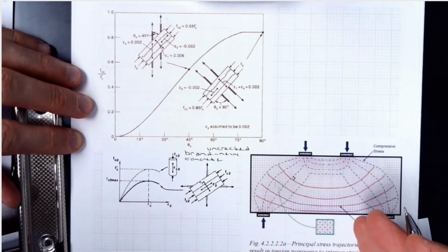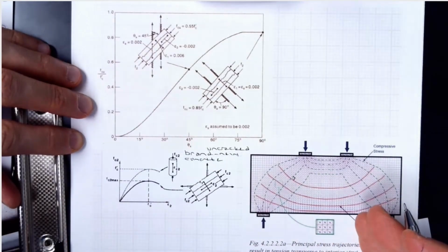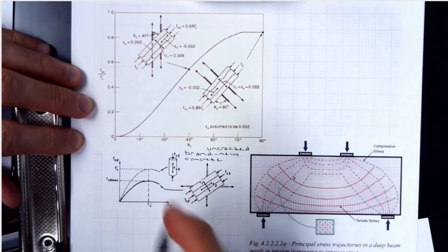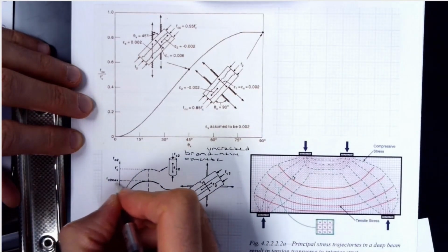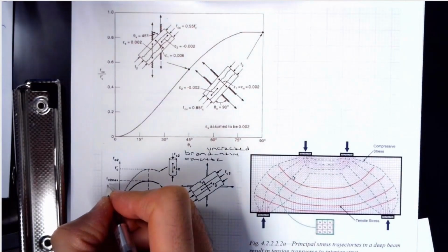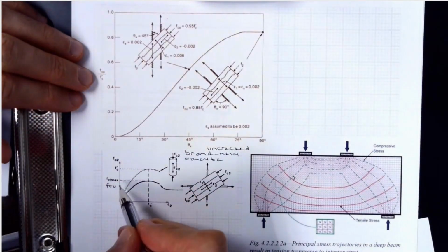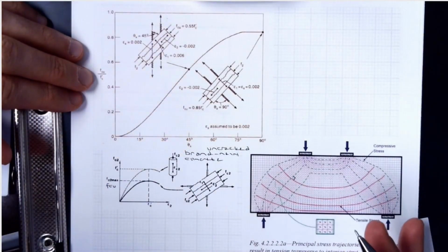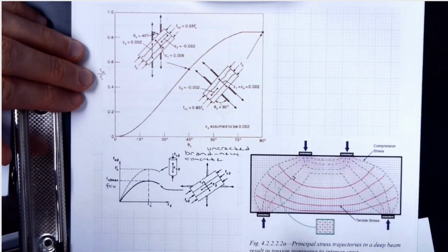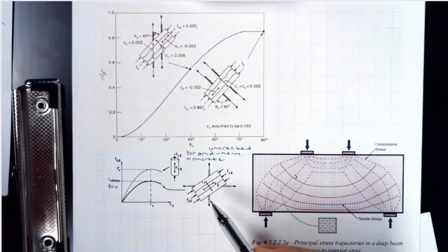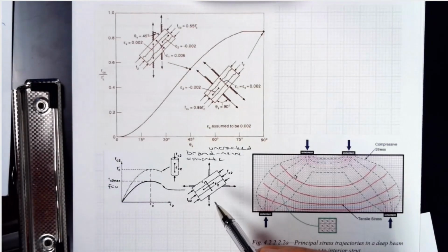So if you have concurrent tension applied on the member, which is always the case for diagonal struts, which is this element, this fc2 max would be the limiting stress, which I defined previously as fcu, which is always going to be less than f prime c. So that's the reason why we reduce it to consider cracked condition, right?